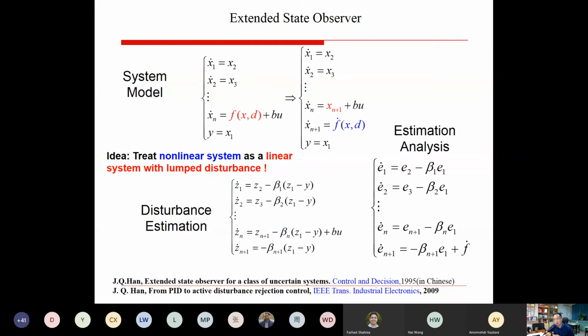So in this case, it's called nonlinear control, not PID. But previously, many people counted it as PID, as an enhanced PID. But mathematically, you see that for the control input, you always have a minus F, the friction, plus PID. In this case, we should regard them as nonlinear control, not PID. So in many cases, for motion control people, if they use friction compensation or backlash compensation, you should treat it as nonlinear control. So I think in the motion control area, most of the so-called PID are actually nonlinear, not PID. Okay, thank you.